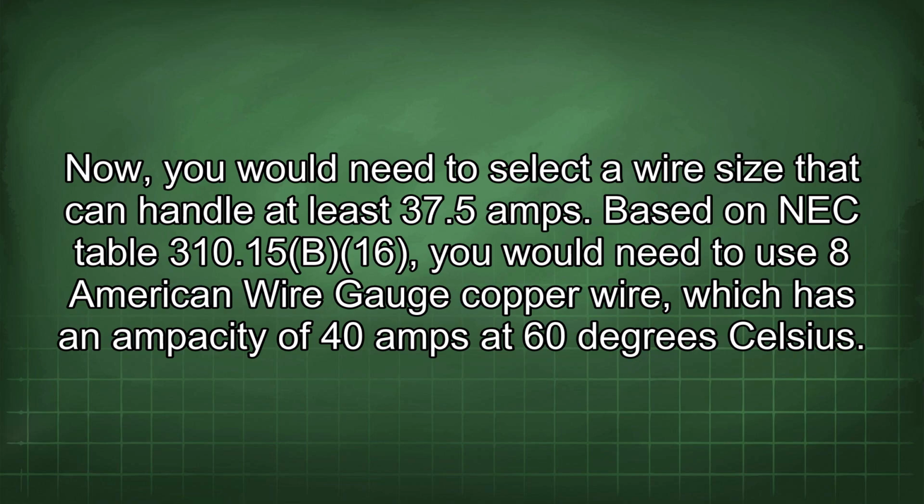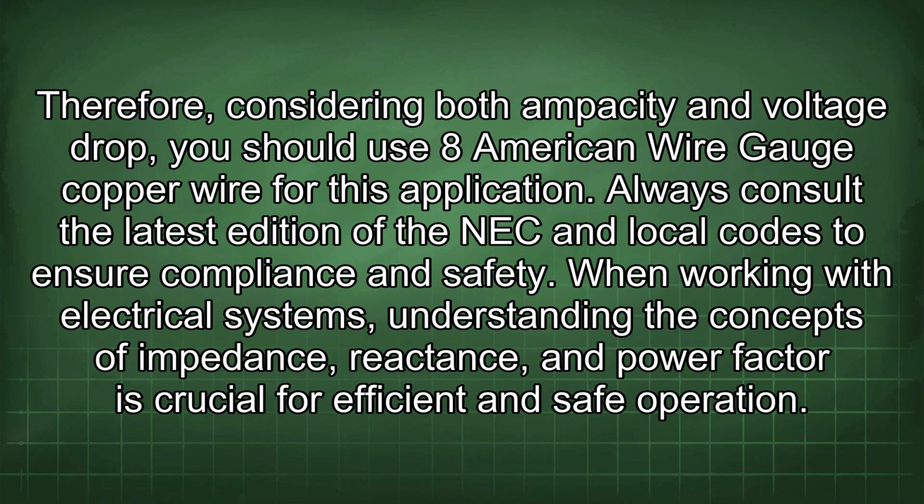Based on NEC Table 310.15(B)(16), you would need to use 8 American wire gauge copper wire, which has an ampacity of 40 amps at 60 degrees Celsius. Therefore, considering both ampacity and voltage drop, you should use 8 American wire gauge copper wire for this application. Always consult the latest edition of the NEC and local codes to ensure compliance and safety.